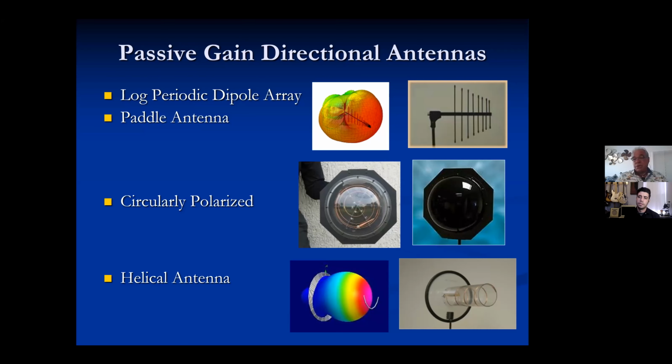What I was getting to is, though, you can actually use a high power two-way combiner, which PWS manufactures, very inexpensive. And you could daisy chain multiple CP antennas under the stage to cover a wider stage. The thing you have to remember is every time you split RF, you lose 3 dB. So if you have two antennas off even a BNC connector, and your Shure is set to 100 milliwatts, you'll only get 50 milliwatts to each antenna.